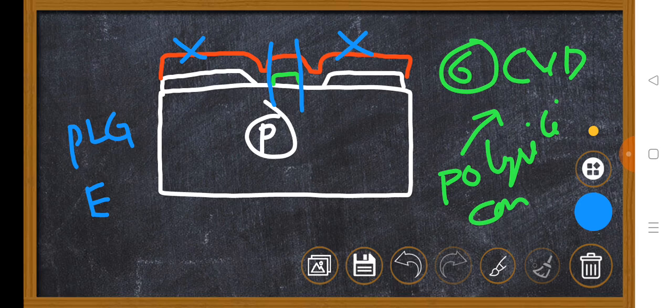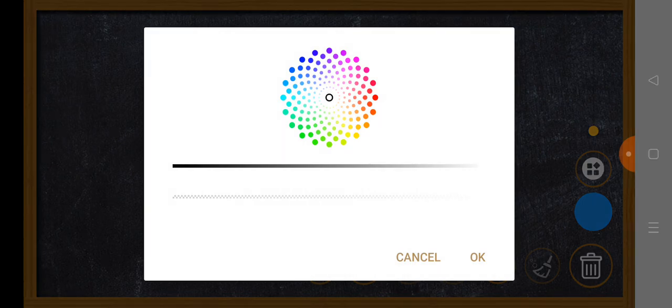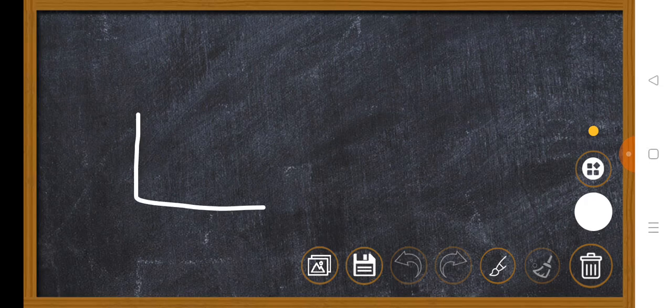Don't forget, before doing the photolithography process, you require a photoresist. After that, you require a photo mask, and you should expose with UV light. I hope you are clear. Now after the photolithography and etching process, how does the structure look, anybody? Yeah, absolutely, the structure will be like this itself.